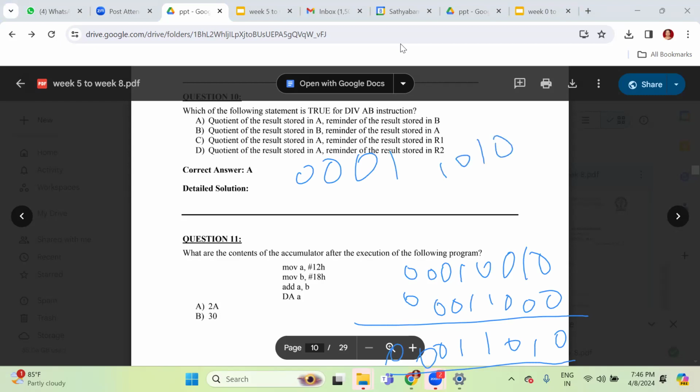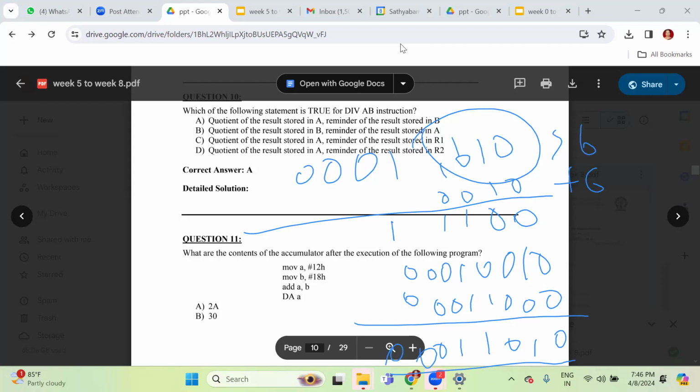I have to check which 4-bit number is greater than 6. I think my lower order bit only is greater than 6. If greater than 6, now I have to add 6 to that bit. We all know I have to add plus 6. So 0010. Now tell me the value. 0101 plus 1010, and 1000.